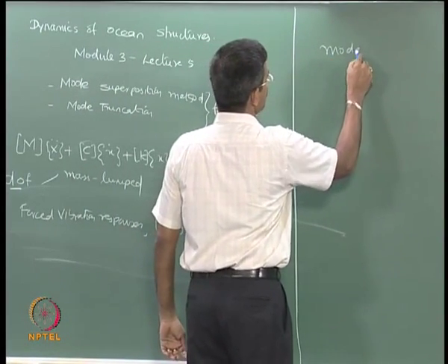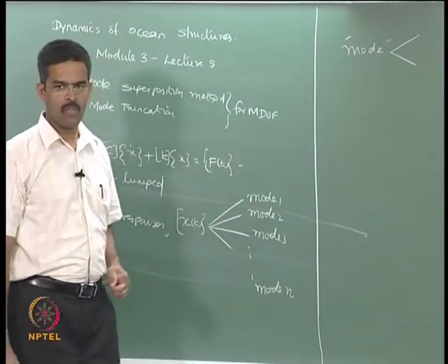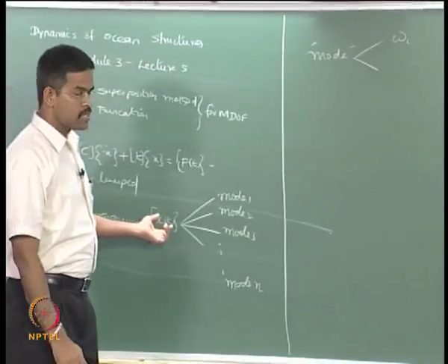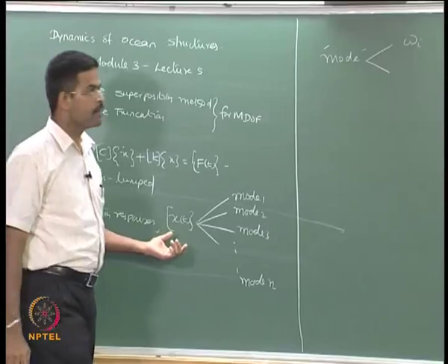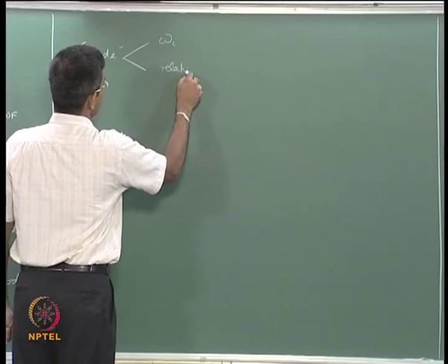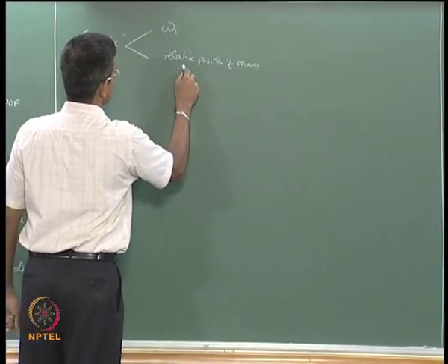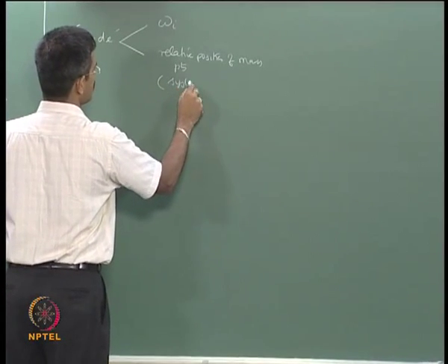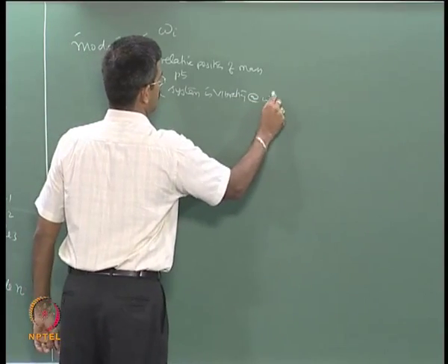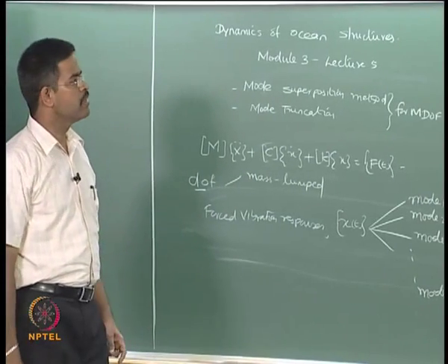The moment I say mode, I have two inherent characteristics assigned to it. One is that I will know at what frequency this response is contributing, and I will also know the relative position of the mass points when the system is vibrating at this specific frequency.